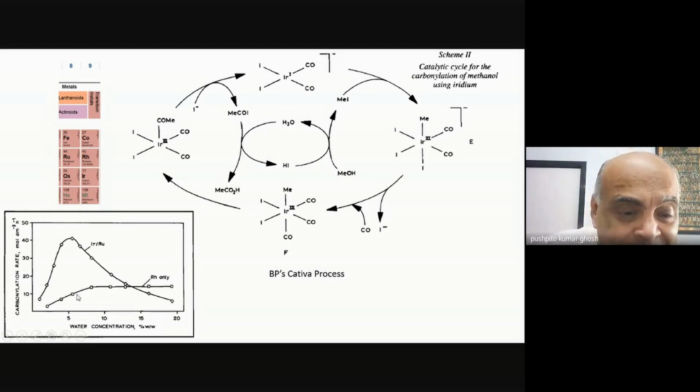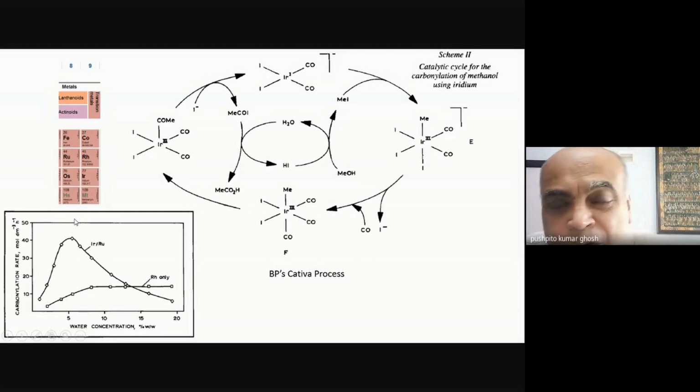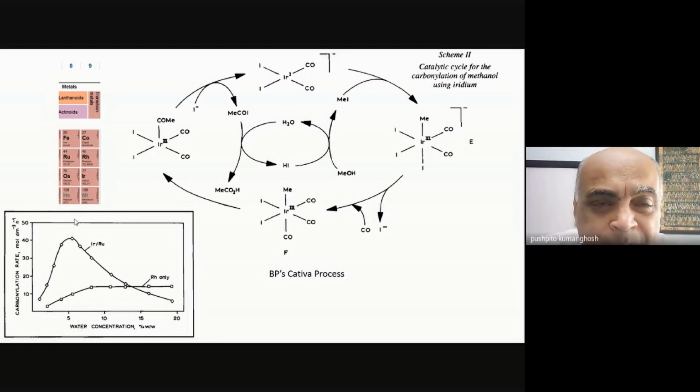And secondly, just like we found when we looked at the platinum rhodium catalyst for converting ammonia to NO, a little bit of rhodium actually improves the properties of the platinum. It reduces the loss of platinum, and it also improves the overall conversion.